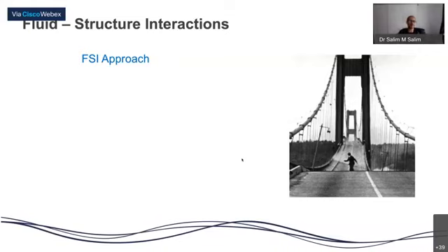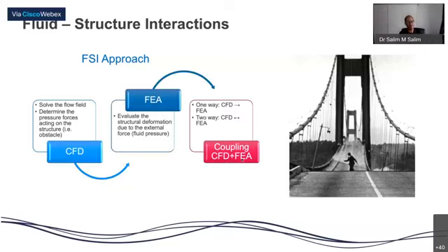How do we design that? When we saw previously the tall building, the Shard, we were interested in the interaction between the two. So things like the Burj Khalifa in Dubai, when you're building tall buildings, or even in Japan, one of the main considerations is the wind loading on those buildings. You wanted to ensure the comfort of the occupants, but also you wanted to ensure things don't collapse. And why is that important? We're going to combine CFD and finite element analysis in something called fluid structure interaction. And that's the new area. If you start doing research, you've seen it in the past decade. So when I did my PhD in 2010, it was mainly just computational fluid dynamics.